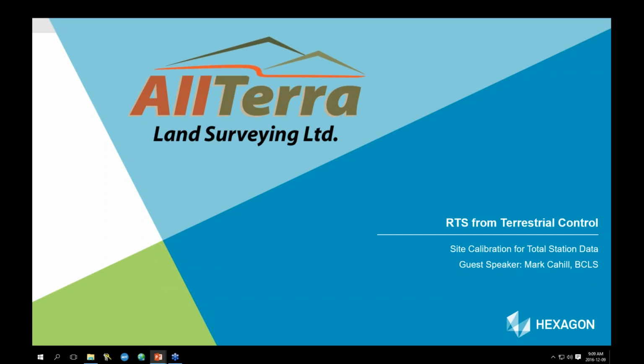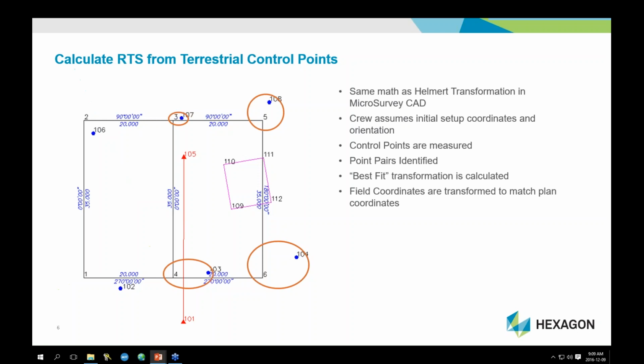I started using a function like this. It's essentially, if those are familiar with the Helmholtz transformation, that's the mathematics we're working with, and lots of software over the years has had a function like this and named in various different ways, but basically a similarity transformation, and we find it super useful and quite a bit more repeatable for the staff, even for inexperienced staff.